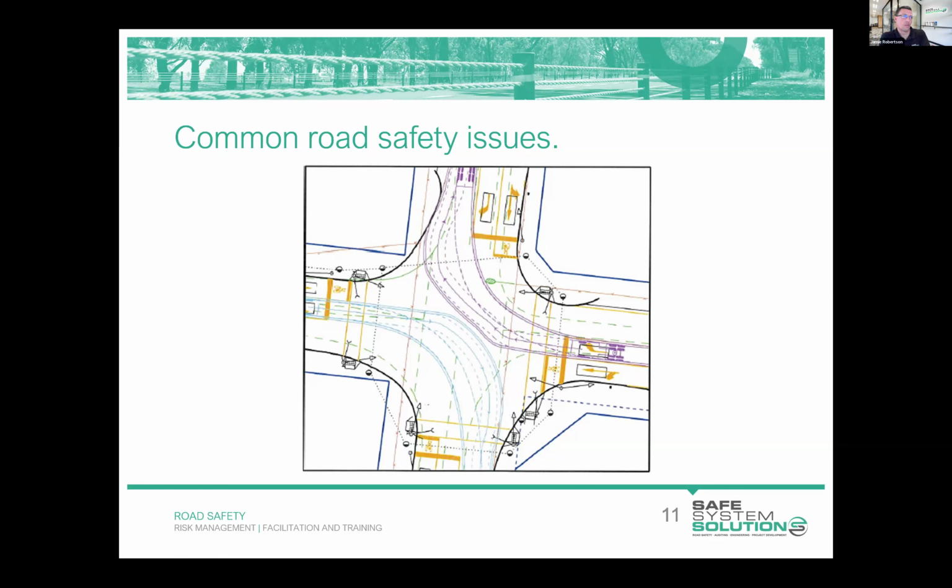So in this case, it appears that the swept path has been manipulated to try and make it work a bit better and avoid the blue swept path coming from the other direction. So you can see there's a convenient offset between those swept paths, but had the purple path been generated in the desirable way, I think you'd see quite an overlap there.